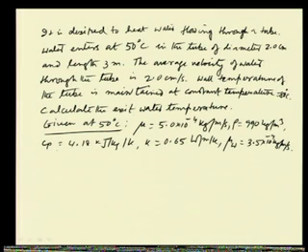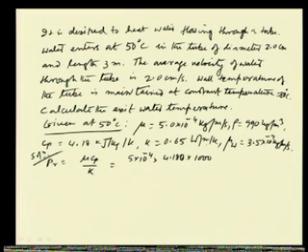Now, the Prandtl number is equal to mu Cp by k, that is equal to 5 into 10 to the power minus 4 into 4.18, and we have to be very careful about the units. It is given as kilojoule, so we have to multiply by 1000, divided by 0.65. So, the Prandtl number becomes 3.22, and let us check the Reynolds number